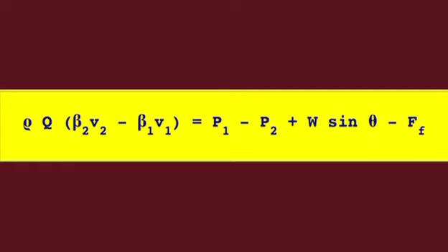According to Newton's second law, the rate of change of momentum, that is, the momentum flux or inertia force, is equal to the sum of all external forces acting on the control volume. The external surface forces are friction and the pressure gradient. The external body force is gravity. The statement of Newton's second law is: in which all external forces are shown here.